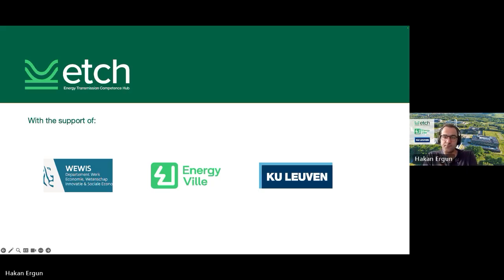Okay, thank you. Another question. The CBA shown in the example does not seem to include intertemporal constraints. Can these be modeled in PowerModelsACDC? Yes, and in fact, they are modeled. Here I wanted to keep the example a bit lean, but PowerModelsACDC also supports storage equipment, for instance, and the unit commitment model includes all these time coupling constraints.